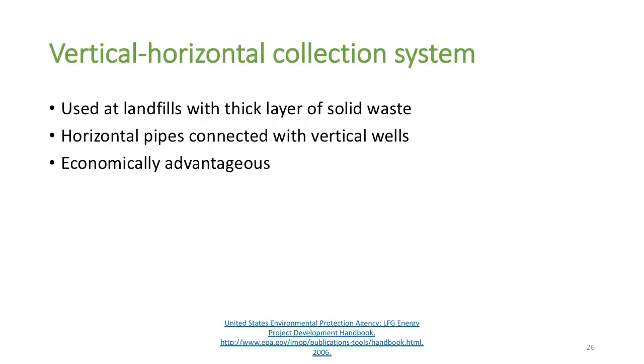And the third one is the vertical-horizontal collection system. It is used at landfills where the solid waste is a thick layer. The horizontal pipes are connected with the vertical wells, and it is economically advantageous.